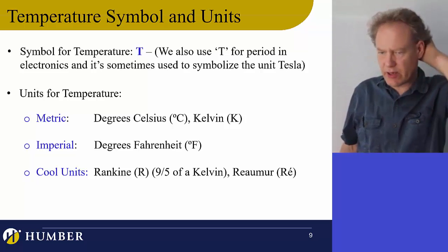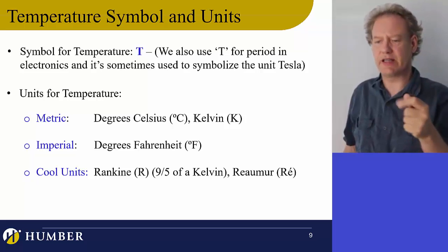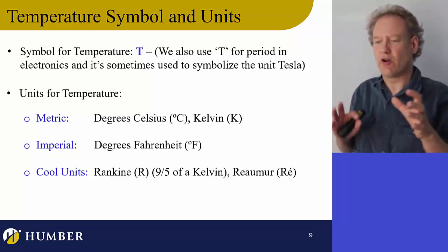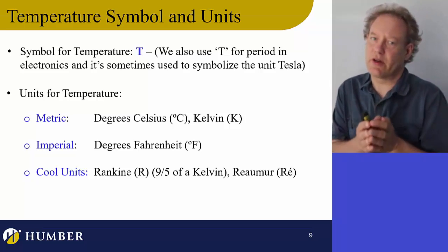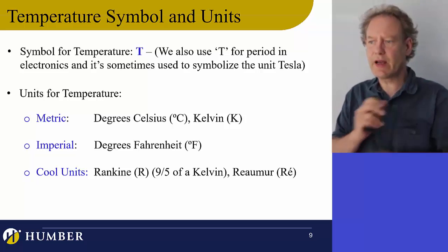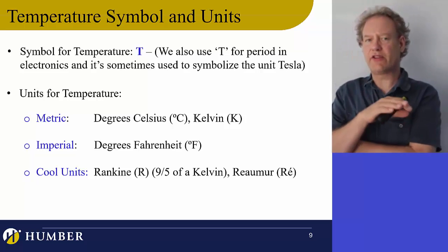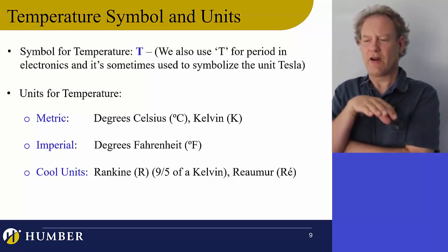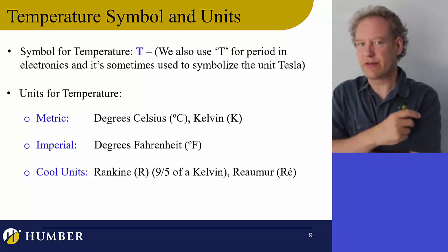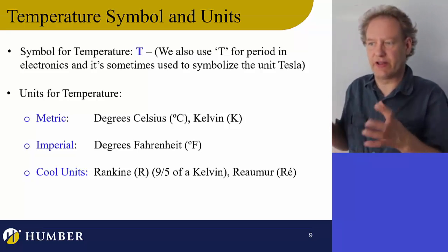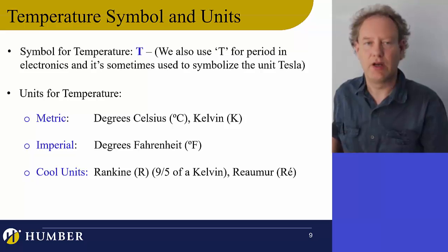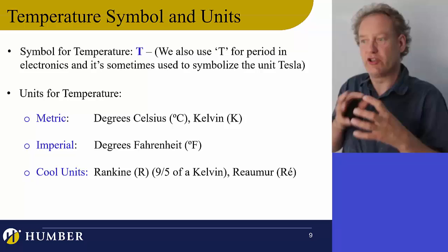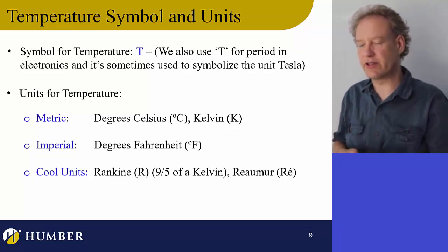It's a capital T for temperature, and we can measure it in Celsius or Fahrenheit or really cool things like Rankine and Réaumur, but we're going to really focus on Kelvin. One thing I wanted to mention is that we have degrees Celsius, we have degrees Fahrenheit, and for Kelvin, we just have kelvins. They're not degrees Kelvin. It's not a degree, it's Kelvin. So watch your words with that, so we're not discussing degrees Kelvin. We can discuss degrees Celsius and Fahrenheit.